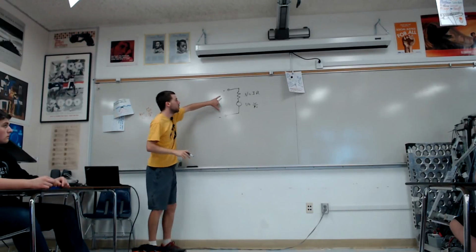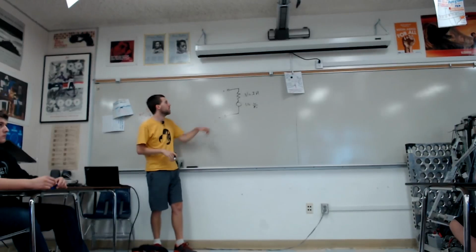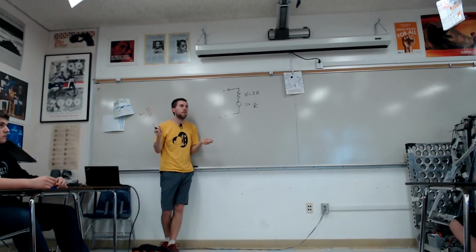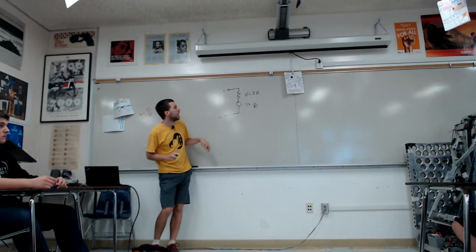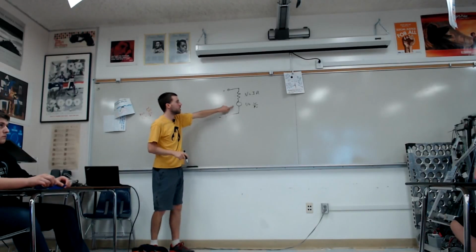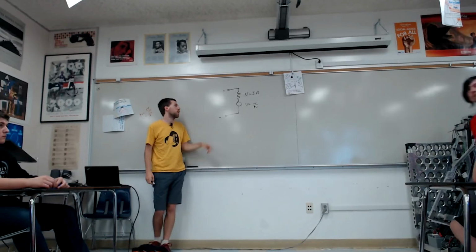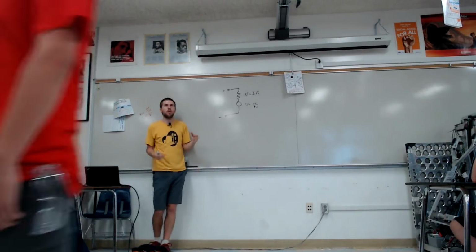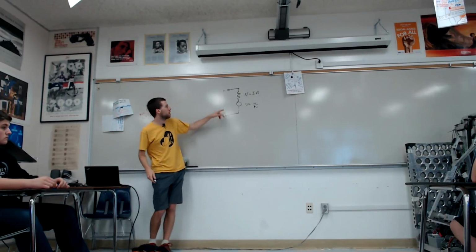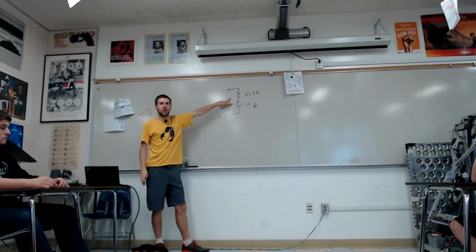So we have two components in our motor, and you can almost find these physically. Our motor has a resistor in it. This is literally the resistance of the copper windings in your motor. And then our motor has a generator in it. When you spin your motor, it generates a voltage. In our real motor, these are not unique components. They're distributed. The windings have resistance, but without loss of generality, we can draw it this way.